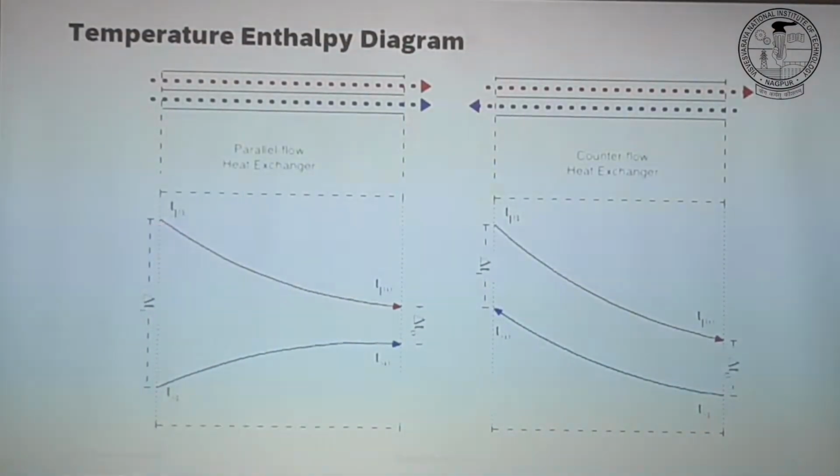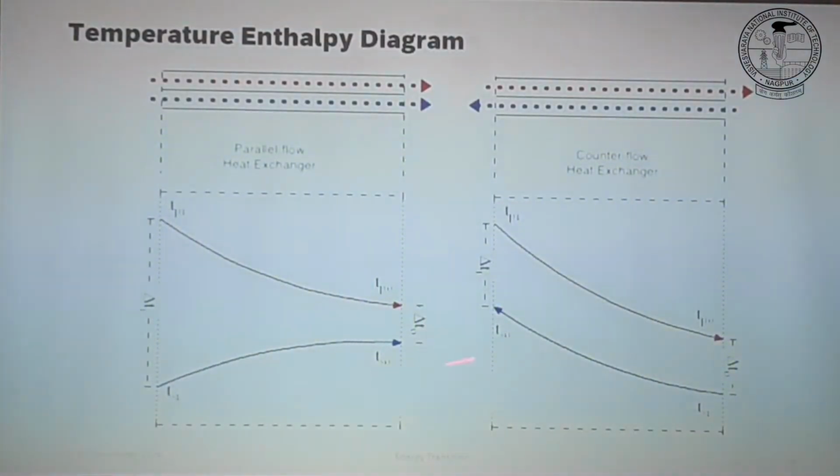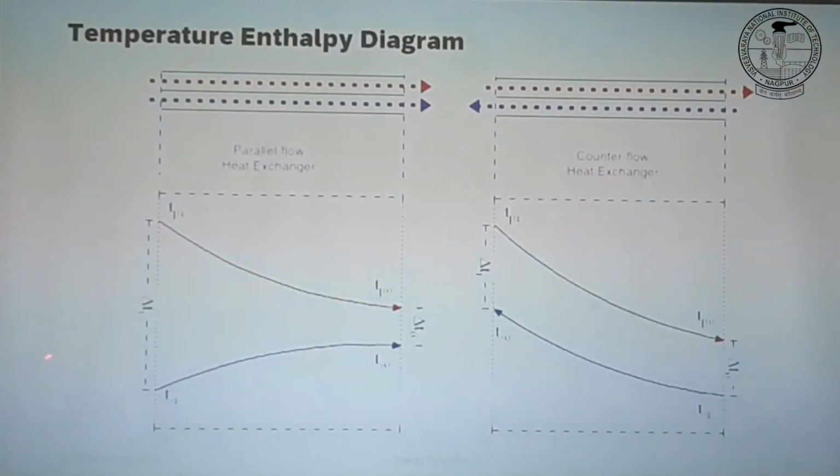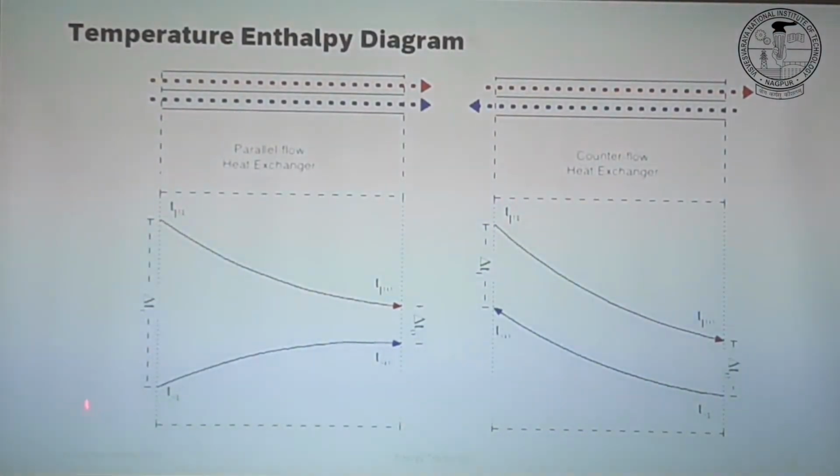The log mean temperature difference we talked about, end to end how we do the overall approximation. But let's do it from here to here, the point temperature difference. LMTD is nothing but representing the point temperature difference over the whole length. So at this point, at the inlet, if I say both are gases, right, so similar heat transfer coefficient, that means the temperature drop would be somewhere around 45% here on the hot side, 45% on the cold side, and the remaining 8-10% on the metal side.